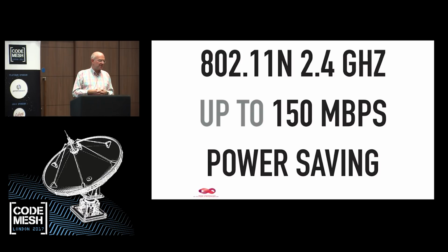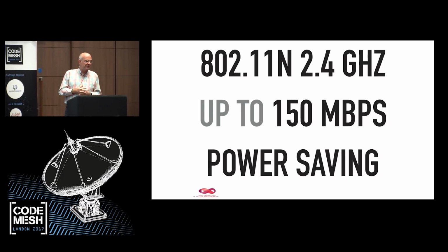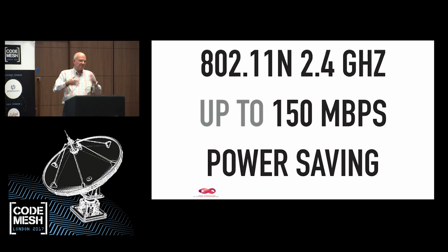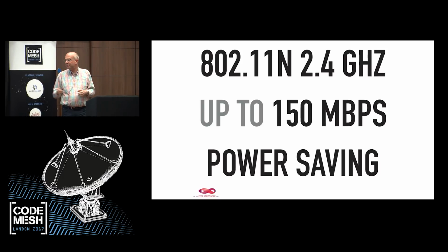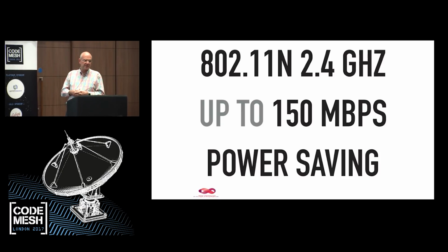I don't have measurements because for the current performance, the real performance, we were happy we got it running. The performance will improve in the future because there's room for improvement. In the USB driver, you can use more buffer descriptors to actually copy more. But we already have a driver that does DMA and kind of does the decent thing. It just needs a little bit of tweaking to get actually more out of it.